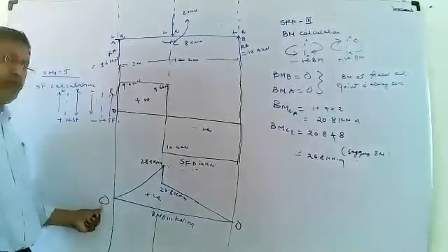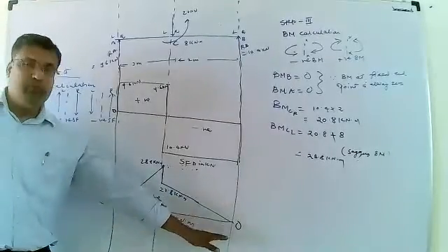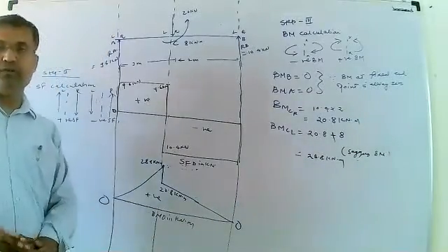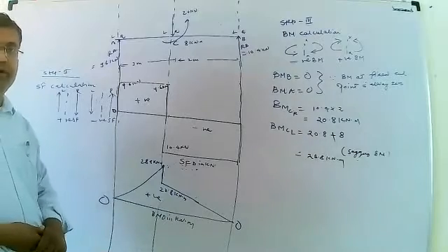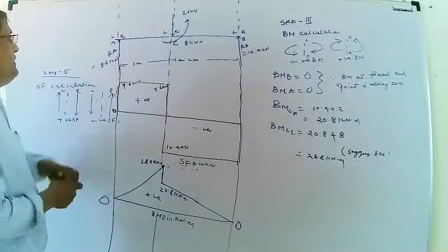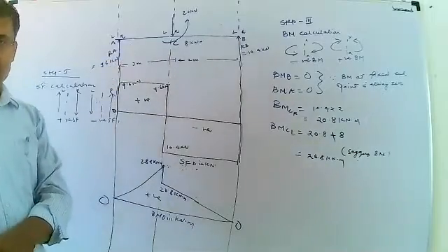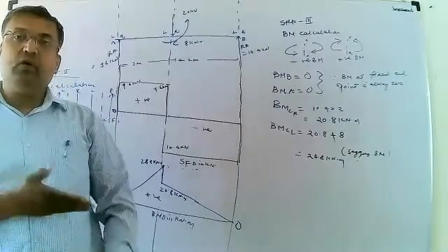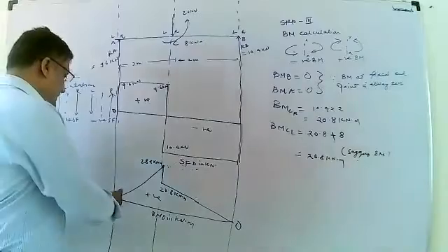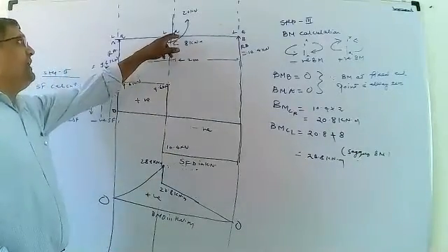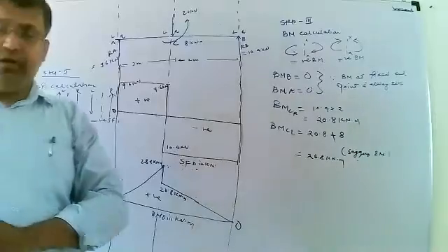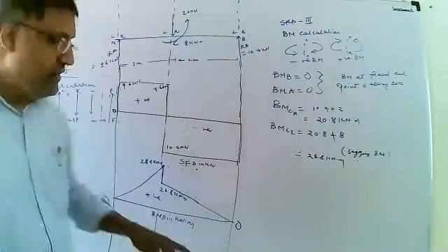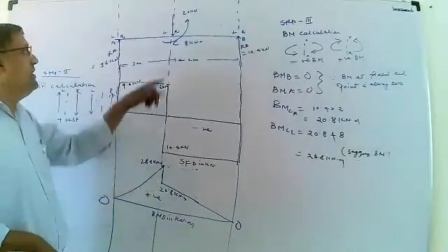Here, if you see, bending moment at the point A and bending moment at the point B will be 0. Okay. Then first we write that 0 on the datum line on the left side and right side of the points A and B. Then in the portion AC, no load is given, and if no load is given, if you want to draw BMD, then draw an inclined straight line. Then here at the point C, a point load of 20 kilonewton is given. There will be no effect in BMD.